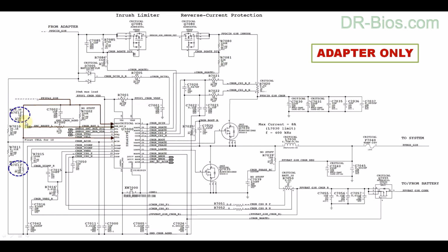This voltage division of the 3.42 volts voltage is for letting the charging IC know which voltage it should generate, and it specifies the final generated voltage of the IC. So if any of these resistors faces a problem, the output voltage PPBUS_G3H will be lower or higher than the standard, which is around 12.6 volts in this device.